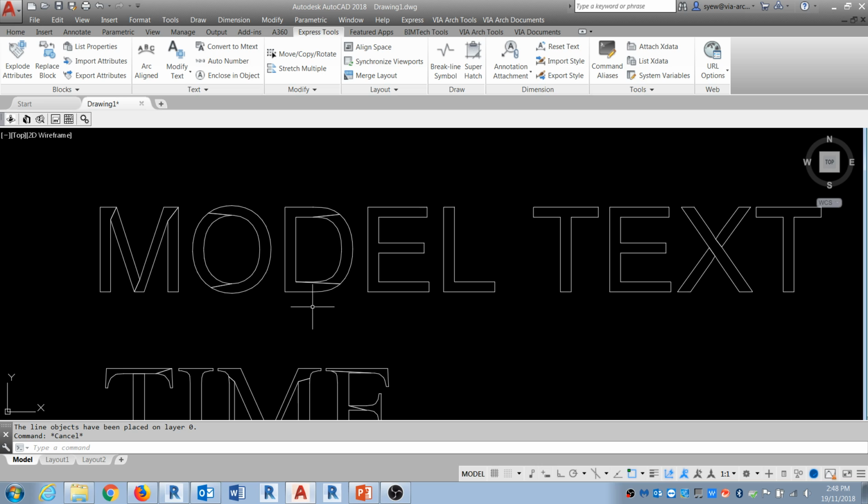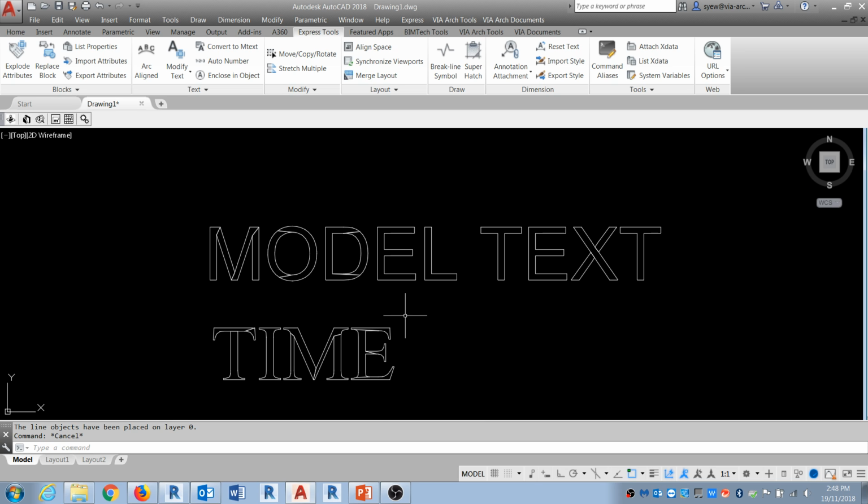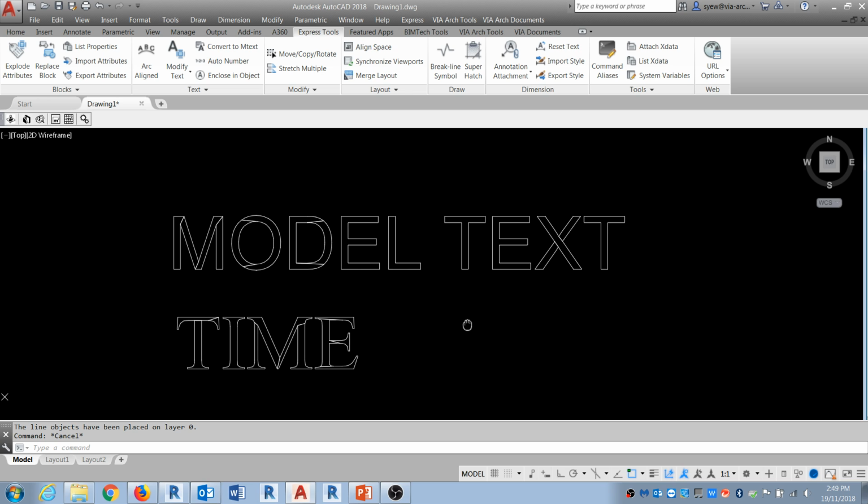So it's a much more streamlined process, so they don't have to go in there and make sure all the texts are the same, because not every user is going to have the same font setup. They may use Mac, I might use PC, so there are variations. If you want to do it precisely, I would explode the text and give it to them in a DWG format.